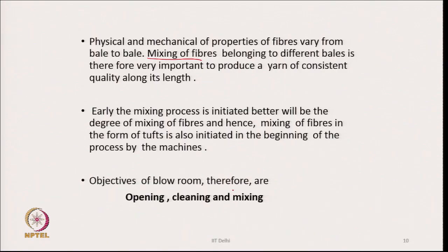Therefore, the objectives of the blow room become opening, through which we will be able to break the bond between the fibers and the trash particles. We will be able to go for cleaning subsequently. Once the bonds are broken, we get an opportunity to extract the trash particles from the cotton fibers. At the same time, we also go for mixing of the tufts. These three therefore become the primary objectives of the blow room.